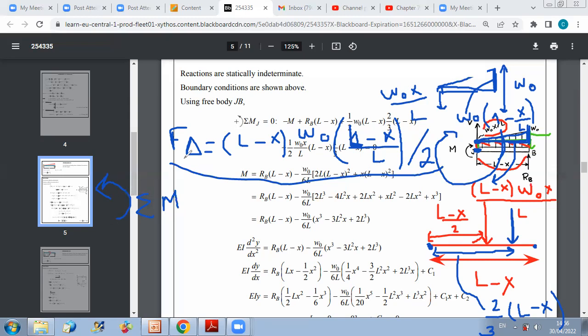Here, for example, we said we want to take the counterclockwise as positive, and the clockwise ones you take as minus. In case you considered the clockwise direction as positive, you can take them as positive. So it's up to you how to take the positive convention. Depending on how you select it, you will see if they produce a positive or negative moment.